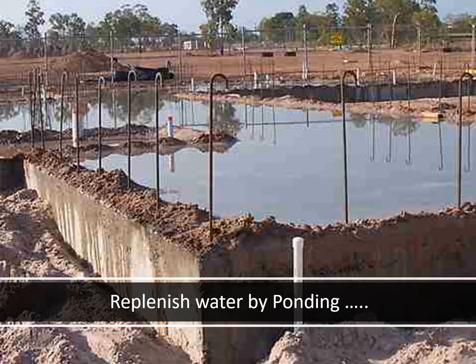Generally in the summer season you need to change the water frequently, you need to recharge the water frequently so that the temperature of the water is maintained at 27 plus or minus 2. Otherwise, the strength of the concrete in the field will be reduced considerably because of the higher temperature of the water. So if you are not able to maintain the temperature of the water, then it is better to change the type of curing.